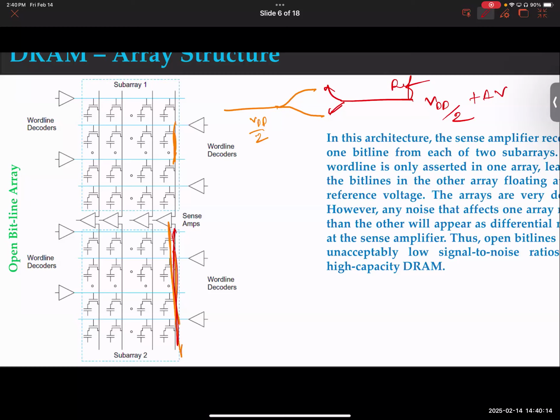And because of that, you can have something coming here, plus delta V, minus delta V. And don't forget variation, right? Like we are considering this an idealistic level, but it's not. There is a huge variation. I'll show you some realistic data from some of our work at some point. But then you'll probably freak out. Oh, how do things even work with that much variation? Okay. So with variation, it's very tricky. If your reference is physically so far out from these cells, it's very challenging.